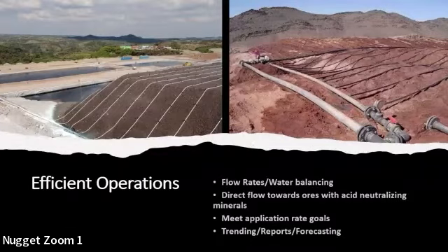First of all, how it came about: we had been performing for over 8 years DCPT, dynamic cone penetration test, evaluations over ROM piles, especially to evaluate bearing capacity for the equipment going over the surface, in terms of what would be safe for operations.